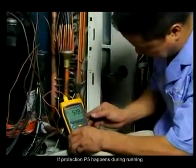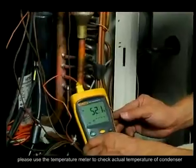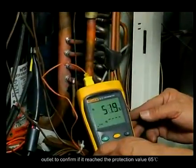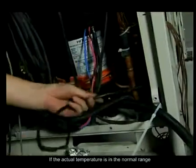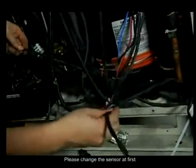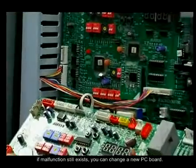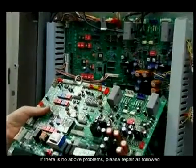If protection P5 happens during running, please use a temperature meter to check the actual temperature of the condenser outlet to confirm if it reached the protection value of 65 degrees Celsius. If the actual temperature is in the normal range, it should be a problem of the sensor or main PC board. Please change the sensor first. If the malfunction still exists, you can change to a new PC board. If there are no above problems, please repair as follows.